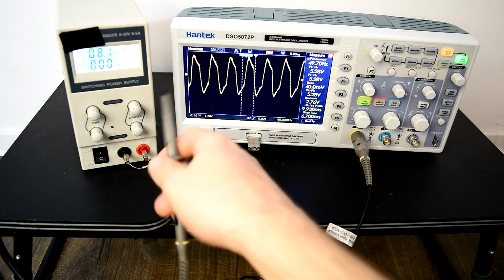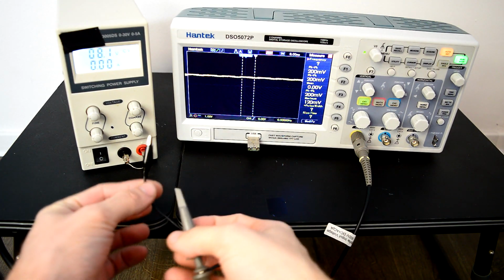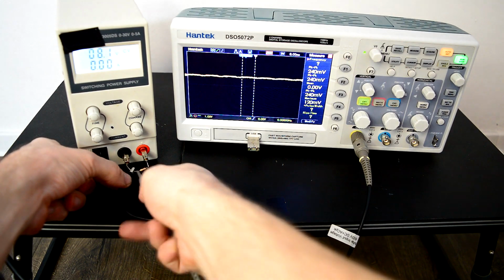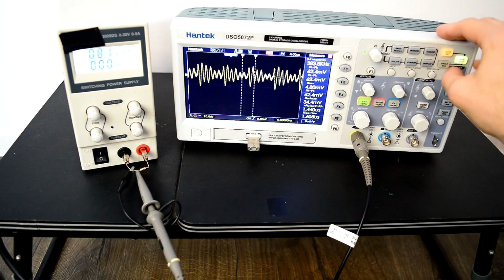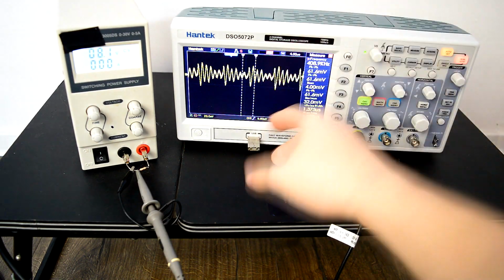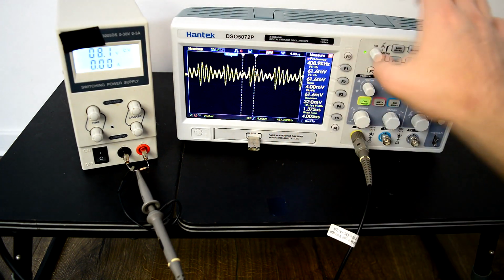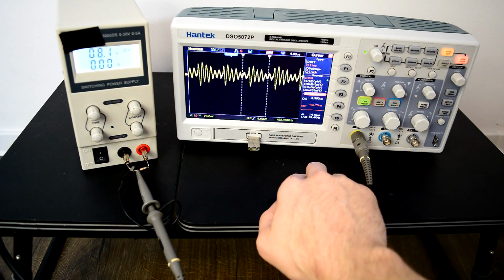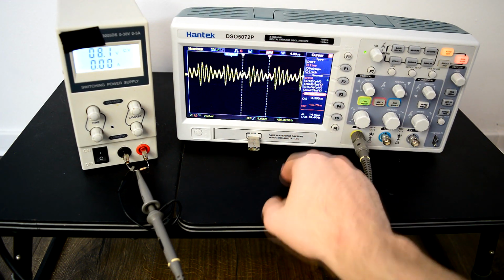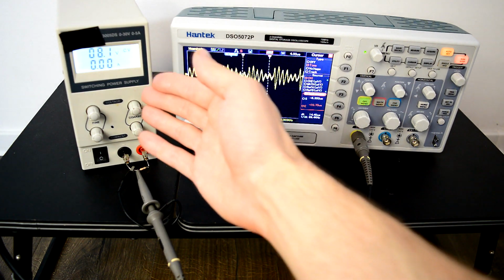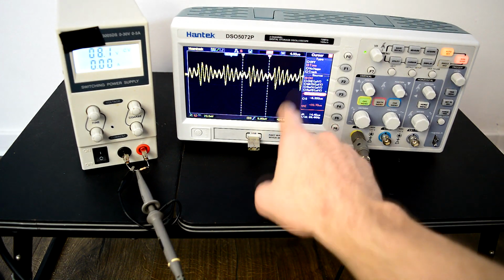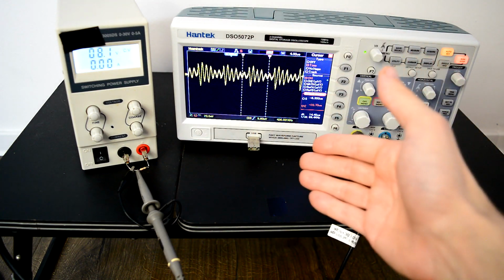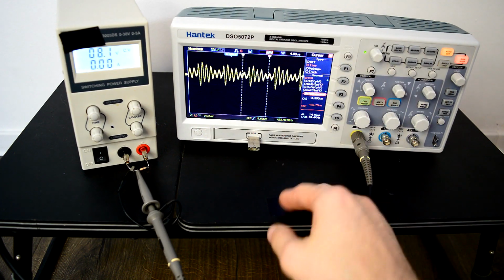Now, just like before, if we connect the ground of the probe to the ground of the supply, and we short circuit the probe, we're going to get this. This is an oscillation at around 400 kHz, modulated at around 70 kHz. So most probably 70 kHz is the switching frequency of the power supply, and this 400 kHz is some sort of ringing or oscillation going on through the system.